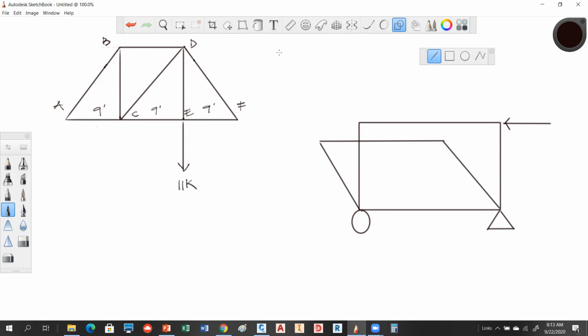Yeah. Okay, so if we make a triangle, what we've done by putting that bracing in there is that this triangle right here is helping to sustain all that load. As a matter of fact, you could actually get rid of these two pieces up here and that truss would be completely stable.